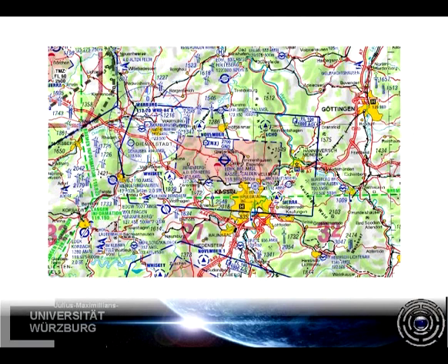This is a VFR chart of the lower airspace around the city of Kassel. As you see, the emphasis of this map lies on the depiction of visible references, obviously. Good examples are these windmills in the west. The numbers depict the obstacle altitude above the sea level. These boxes show different airspaces and their horizontal and vertical extent. In different airspace classes, different rules of the air apply and have to be followed by all air traffic participants sharing it.